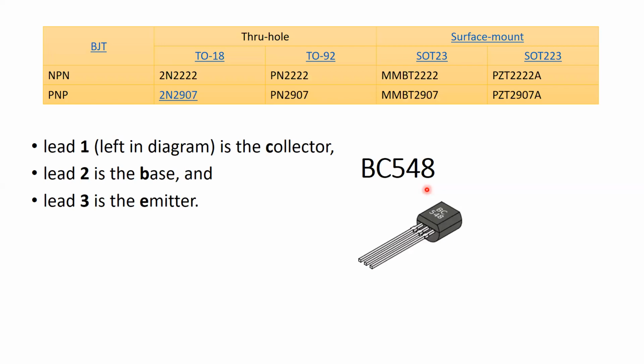So hope you understood the basics of the part numbers, and when you actually choose these transistors, depending on your application, like I explained, for general purpose amplification or switching applications, you go for 2N2222 or BC548. Whether it's a plastic package or metal can package, it's a discrete transistor. Go for a datasheet from the manufacturer, just search Google. And then when you want to use this part, first task would be to use the simulator to verify the functionality of your circuit. That we'll do later.